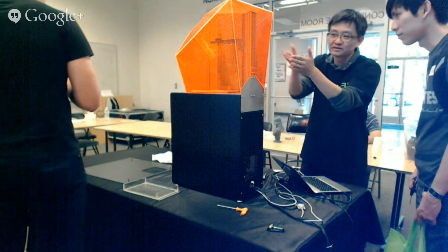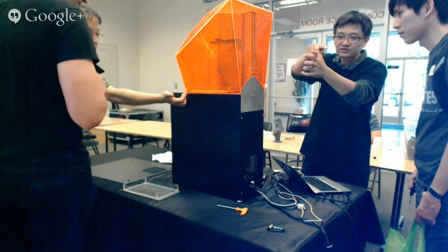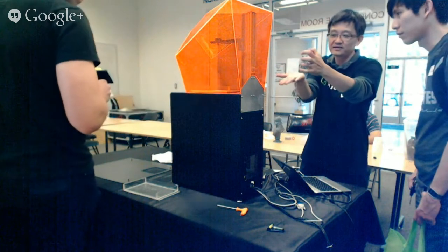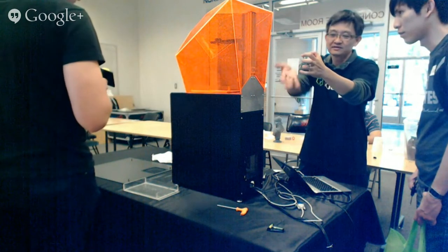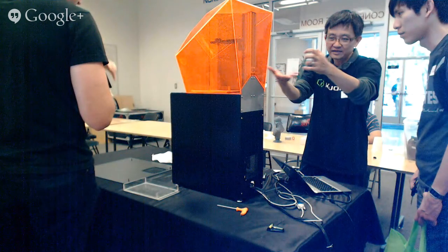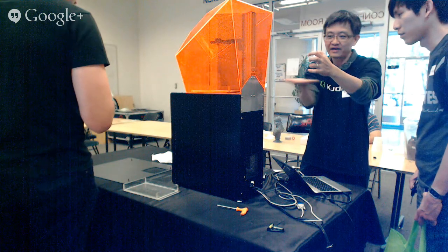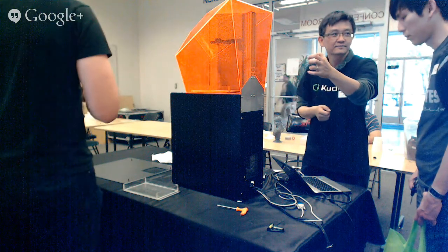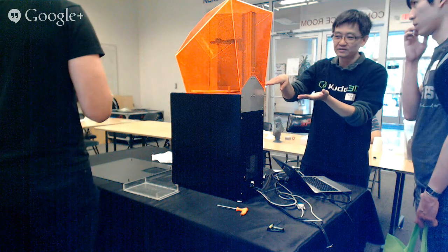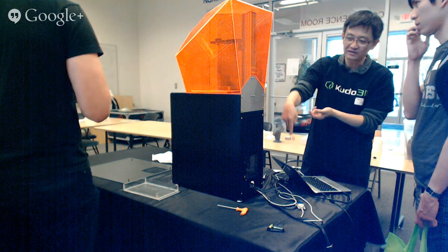Which means there's a difference in forces on this end compared to this end. So how much differential is my part taking? In this case, very little. And more importantly, my part is still a bunch of dots even as I go up. So as I go up, I'm not building a structure that's going to cause the forces from one side to get strongly transferred to the other side, and that would create the flexing.